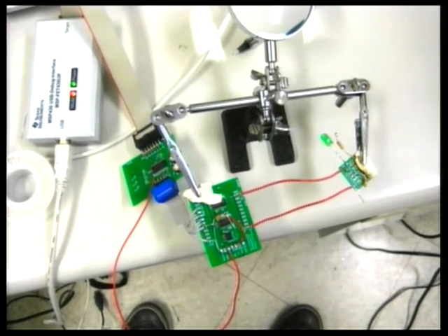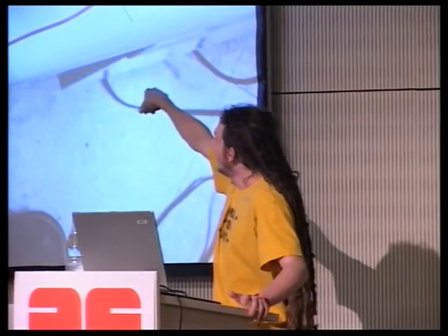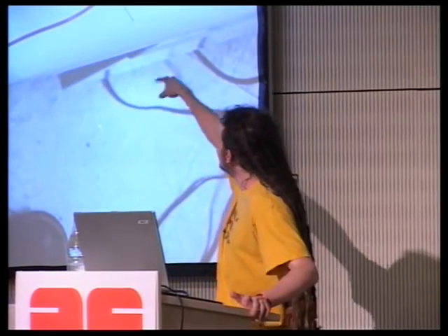But in this layout I had a modified BSL cracker, and then I've got a voltage glitcher, and I've got my business card. By triggering the glitch, I can make the business card skip into the section of its code that starts blinking that LED.